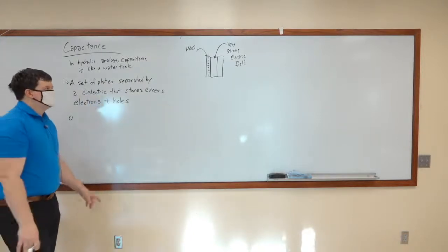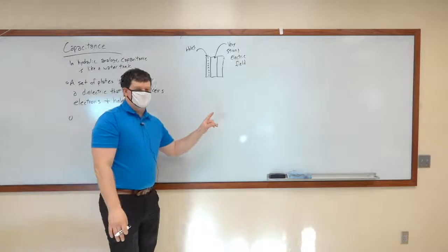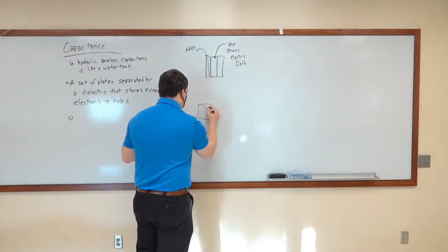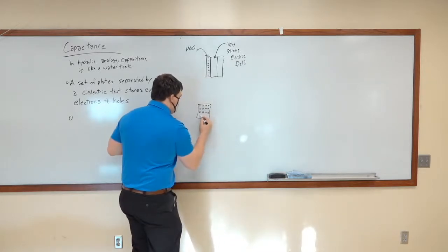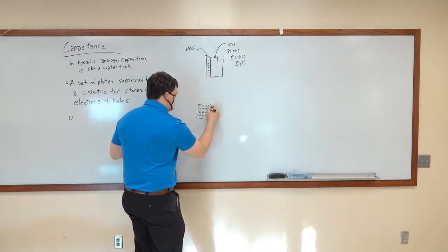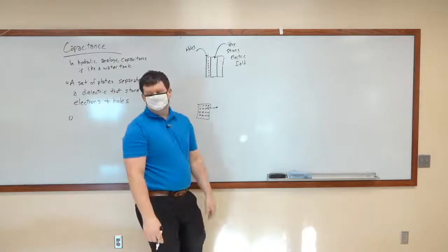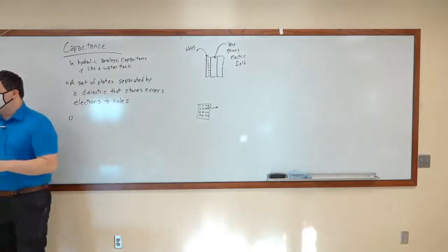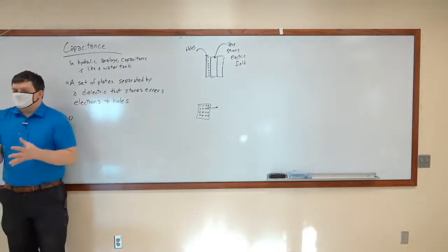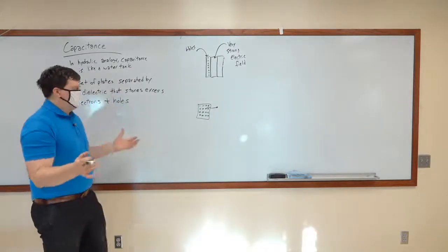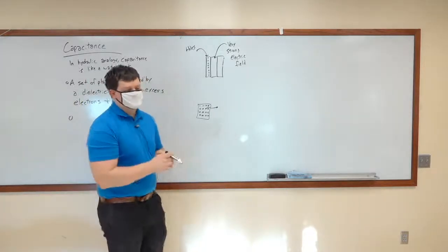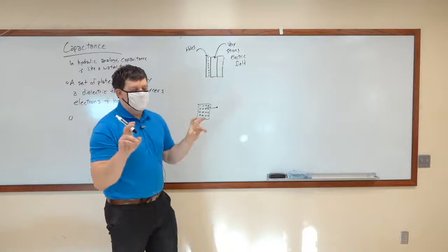We refer to this as holes in physics, because you have a material that is supposed to have X number of electrons in the matrix, and some of those electrons leave, leaving electron holes. They aren't real physical holes. They're just energy locations where electrons should be and are not. That is the definition of a hole.